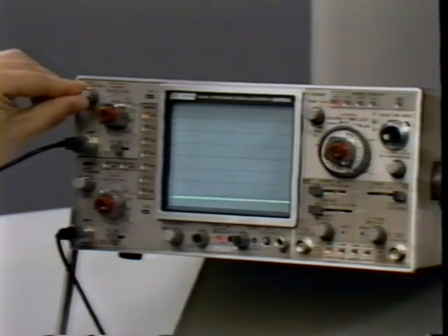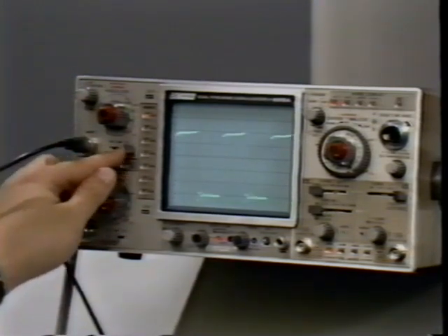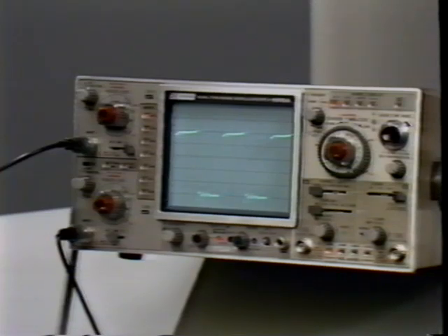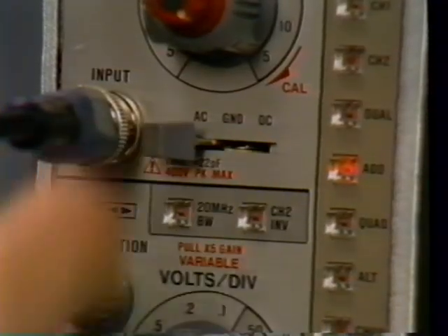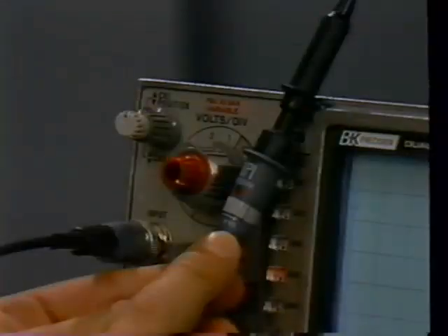After setting your reference point, move the input coupling switch to either AC or DC. Use DC when tracing TTL or other logic signals. Use AC for differential outputs and for signals such as power supply and video output transistors, where the signal rides on a large DC level. If you are unsure of the type of signal you are going to observe, start with AC coupling. This will help prevent overdriving the scope, and the signal will tend to settle onto the screen.